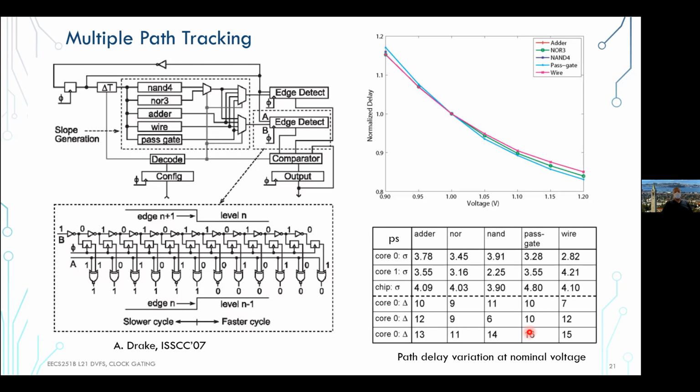And then some number of, this is actually picoseconds, and then some number of RMS variations, because you can actually disperse these measurement circuits throughout multiple cores, wafer to wafer, and look at all those statistics to figure out, is your technique robust across a million chips or 10 million chips that you're going to produce for people, not just on one wafer.